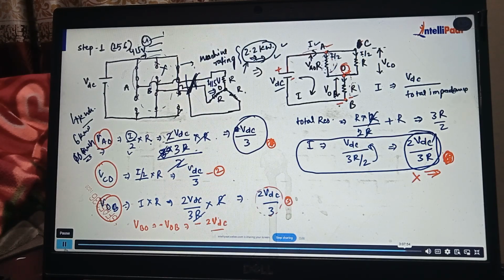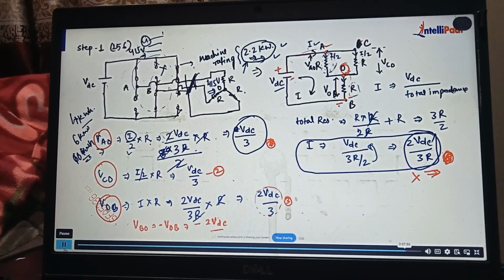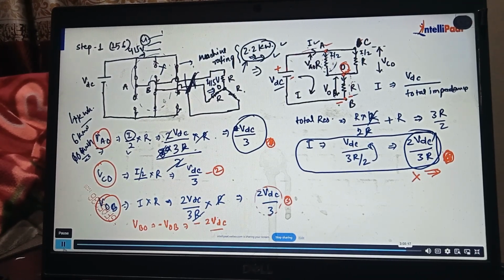Though the voltage could be unbalanced and the frequency may not match the frequency of operation, to get voltage at our output side we have to complete the circuit, that's all. So even if one switch failed, it should not be that both switches from the upper side fail, or one switch from the lower leg fails. Otherwise, the circuit will not be completed. Partially works. Yes. Suppose the switch of the B leg, the lower leg, is failed. Then you don't have any connection with the negative DC bus. So in this way, this converter won't work.